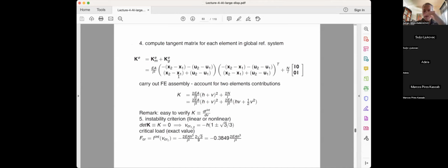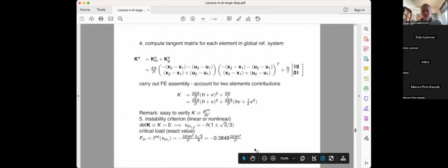If you have, for example, very slender structures moving a lot, you cannot apply linear theory. Let me put it this way, on the whiteboard. Anytime you have a situation of this kind, this is your truss bar, and it has length L. If I extend it just a little bit, the deformation epsilon is equal to du dx,